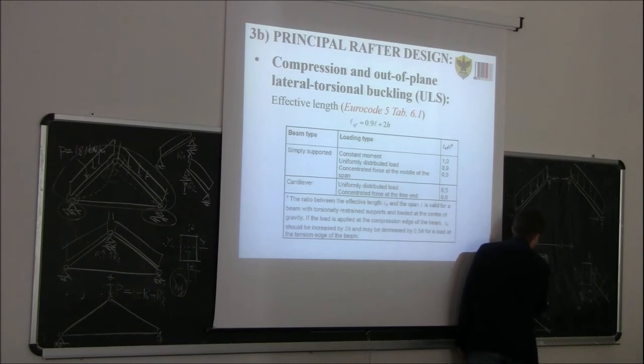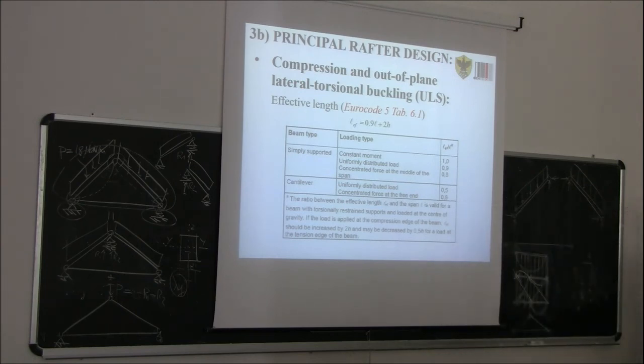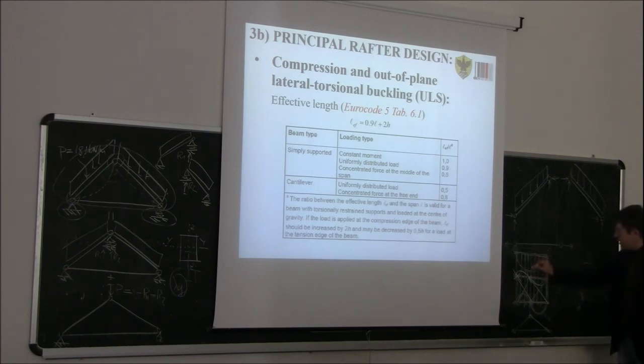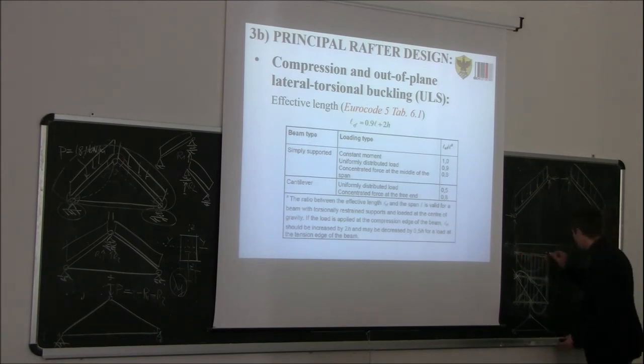Now, if I put a bracing here, I'm sure that this is fixed. Of course, also this is fixed. My question is, what about this? Not possible now. Why is it not possible? Because now the purlins are fixed. Now the purlins can work. In reality, they will never be fully rigid, but for sure they will have some strength to make also this point fixed and also this one fixed.